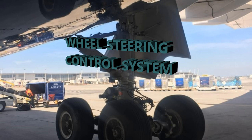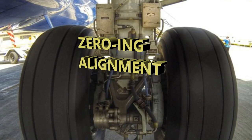Okay, and then the last thing just to mention is the zeroing of things. Zeroing just means you're aligning things, and in particular I'm talking about electrical and mechanical zeroing of your components. With the electrical zero, I'm talking about the rotary variable differential transducer that would need an adjustment. So there's an adjusting that can go on here.